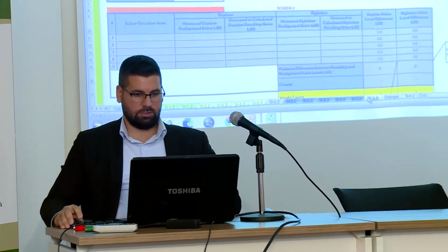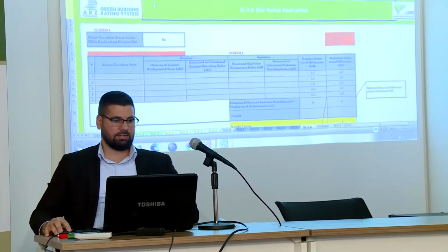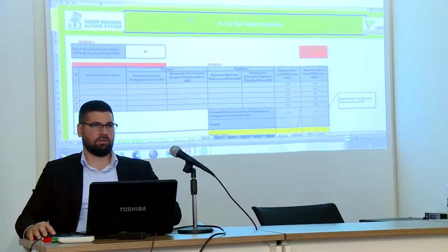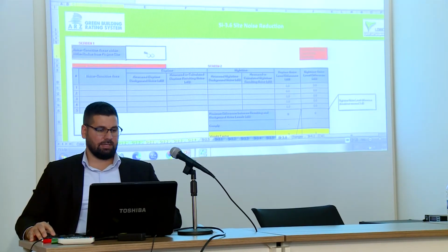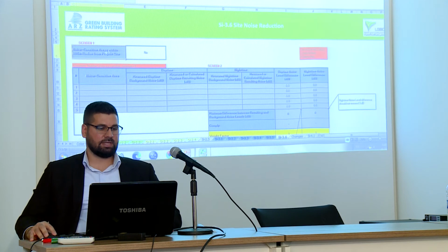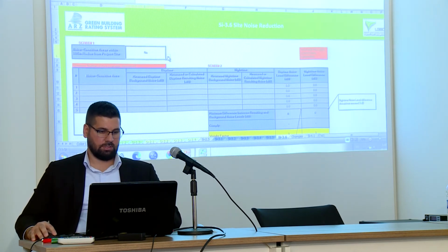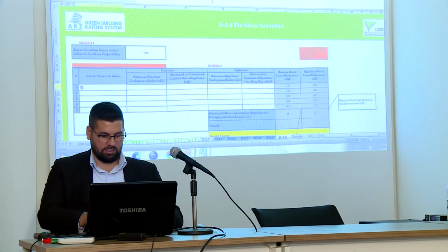Okay. Next one is site noise reduction. This is related to the impact that our site is having on the environment and on the neighboring buildings. Mainly, we have to check if there is any noise-sensitive area within an 800-meter radius from the building. What we mean by noise-sensitive areas are schools, wildlife, maybe a small forest, a nature reserve. If we have this, we have to check this criterion and check if we can earn a score on it. So let's say we have a noise-sensitive area, a nearby school.